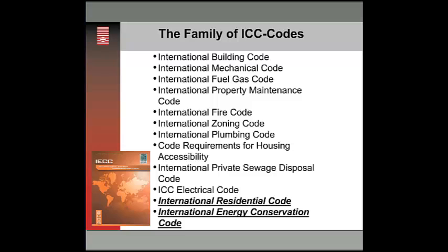and have at it. But the family of codes would include the IBC International Building Code, IMC International Mechanical Code, Fuel Gas Code, Fire Code, Plumbing Codes. The ones that we're really concerned about are the IRC, the International Residential Code, and the International Energy Conservation Code. Historically, they have been two separate documents, and some of the provisions of the IECC have been incorporated by reference into the IRC.